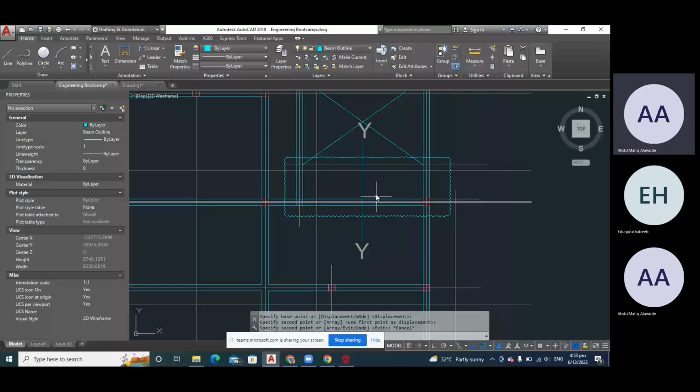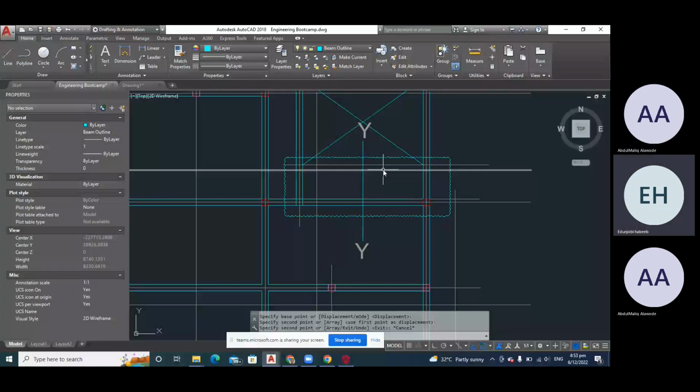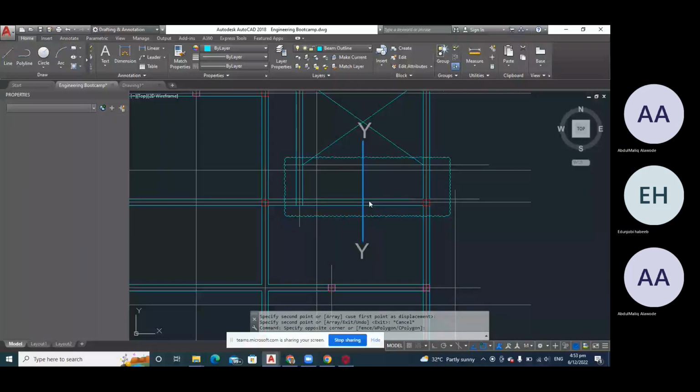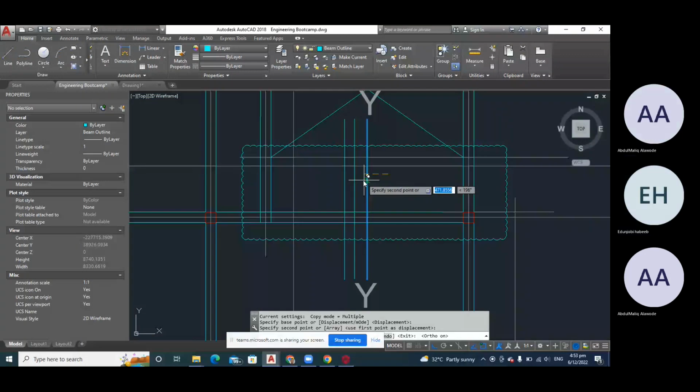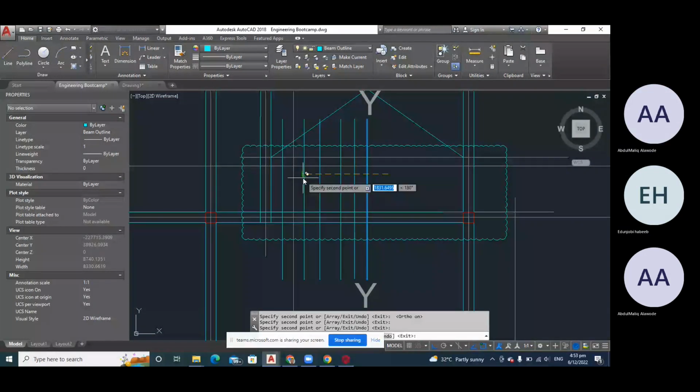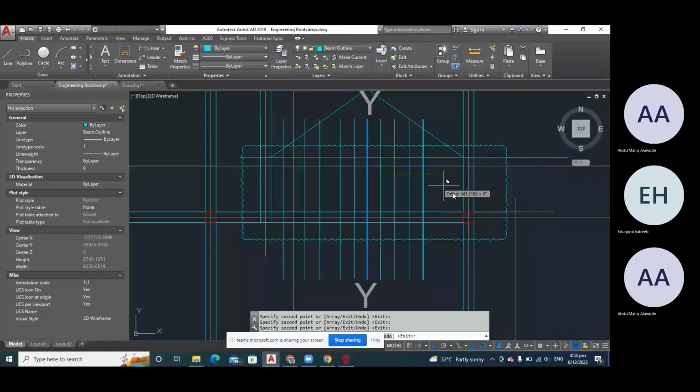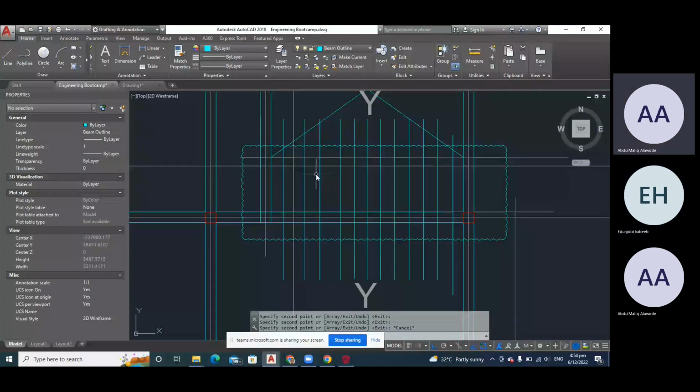So my bottom reinforcement, that means when we get to site, the first set of reinforcement they are going to lay is along this axis I have drawn. Just assume they are going to first lay the net with the right spacing. Have you seen what I've done? Yes, sir. This is the case when we strip this slab on the Y axis first.